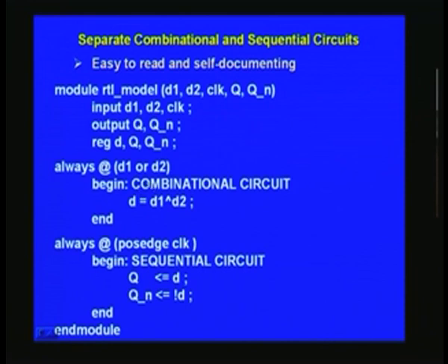Or you can just, for improving the readability, have this. It's a good practice to have this. And this does nothing more than take the exclusive OR of two inputs and assign it to D, and that's what this logic is doing. This is just a D input for a flip flop, and the flip flop is written in a segregated block here, which is also an always block, and the action is taken at the positive edge of the clock. And for simplicity, I have omitted the negative edge of reset, which we considered earlier.